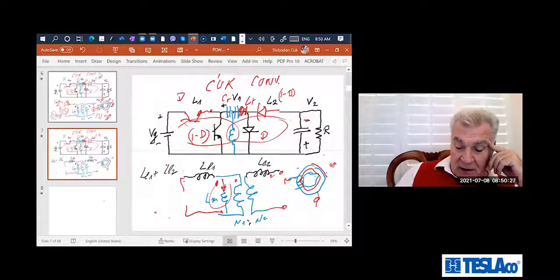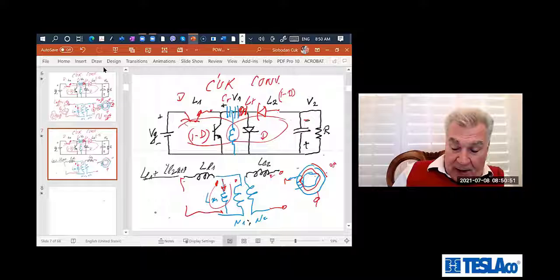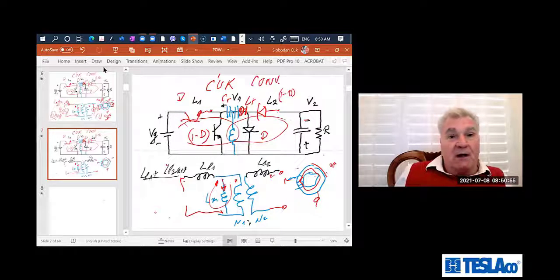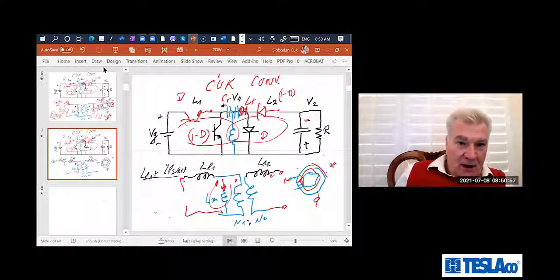This inductance, reflected by the turns ratio squared, is the inductance on the primary, and let's call it L2 reflected. 60 hertz people will prefer this model. In fact, that was my problem when I invented the coupled inductor. So I just give you an upfront view.